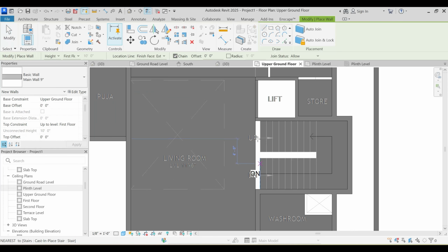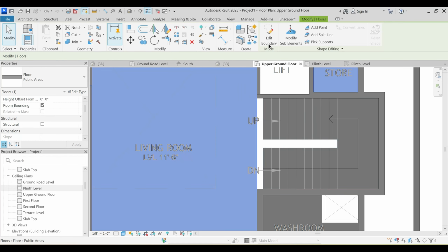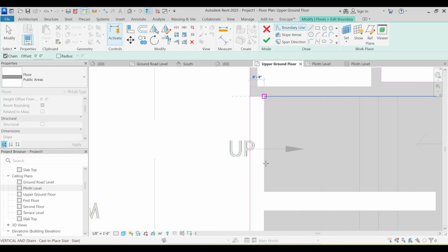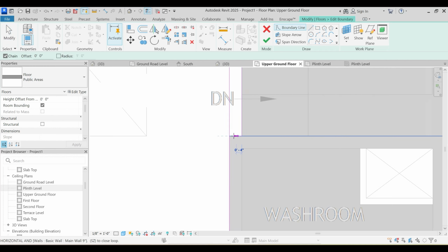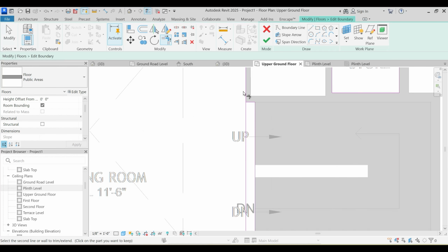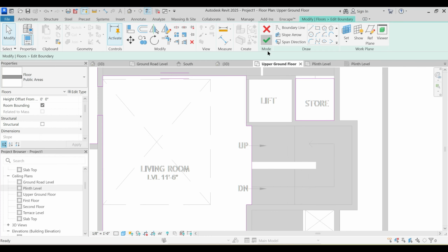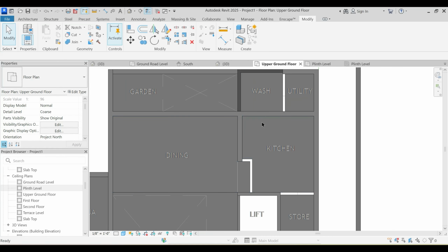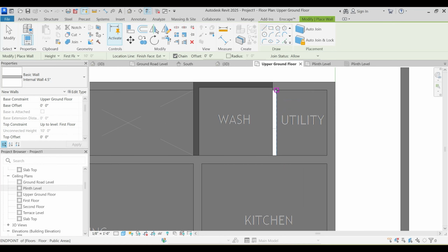here there will be a parapet wall. No, here there will be no wall. Here, the floor plate would go inside and split. TR, join this to this, join this to this, and just finish. Don't attach. Perfect. Only the internal wall needs to be created. So I'll just change this to internal wall and the constraints remain the same.